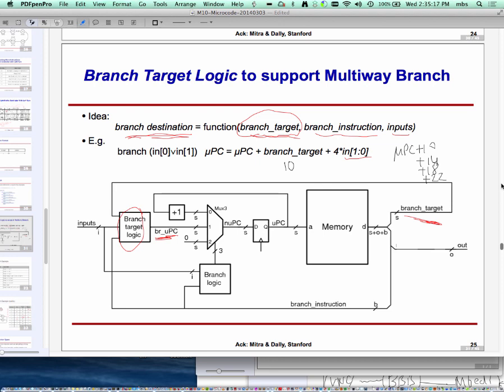So what's happening is I'm only able to jump to some specific addresses now, not arbitrary. Whereas in the first type of microcode, without the branch instruction, I could specify anything arbitrary, but then I needed more words in the memory. So that's really the trade-off that's happening.